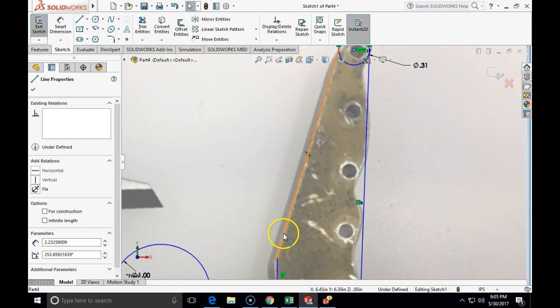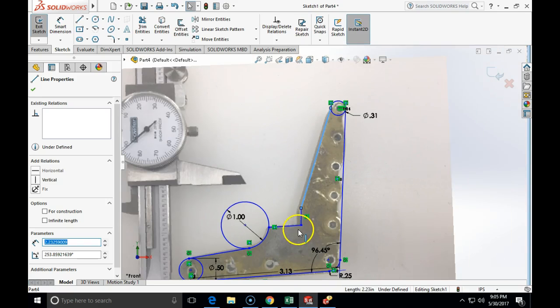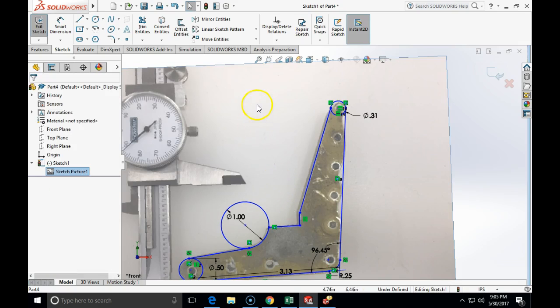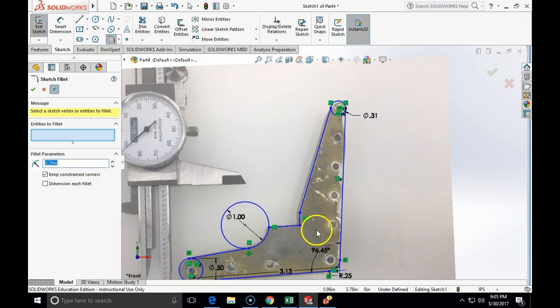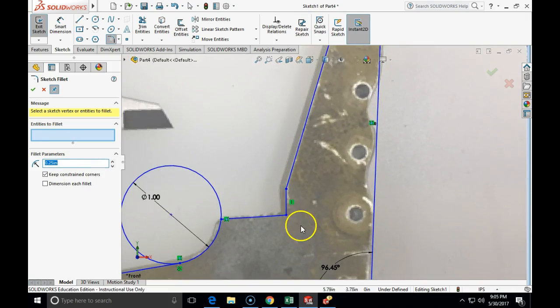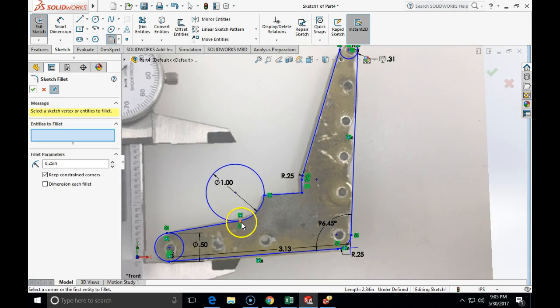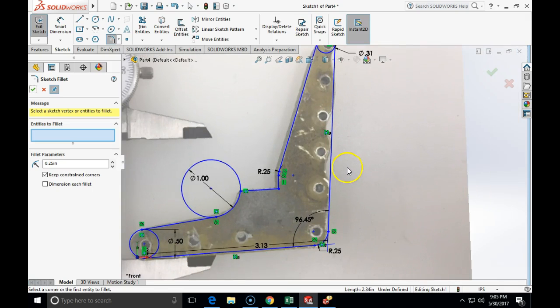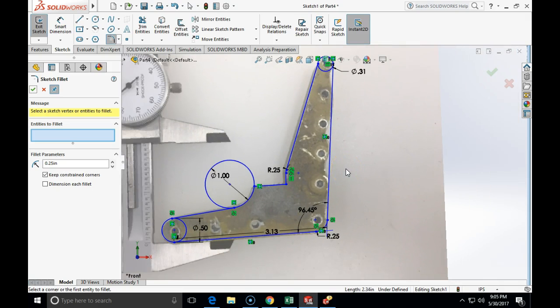And so on. So we will move it, and as you can see, we get a little bit of tightness. So we can now get another fillet here. And that fillet is very small, maybe 1/4 inch. That's correct. And let's see, that will be a fully defined outline. Now we need to get a relationship to our center, and how can we do this?